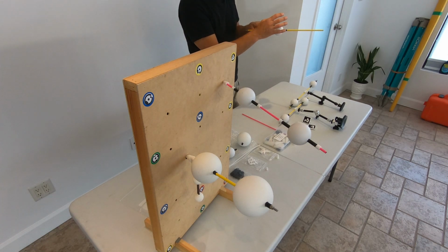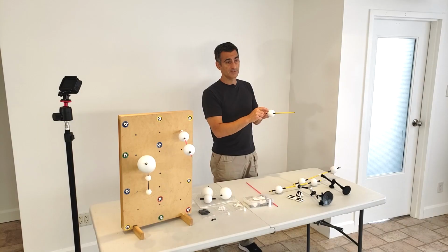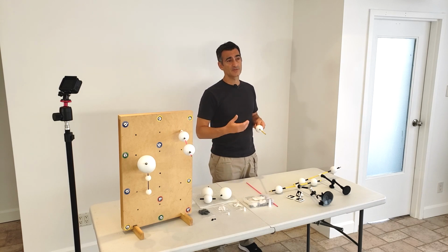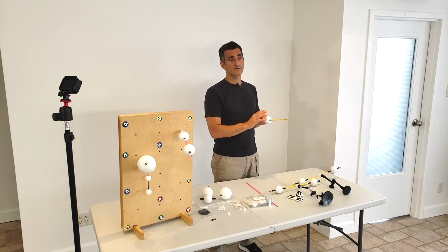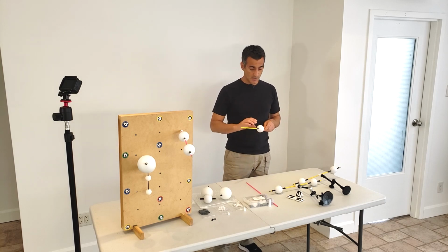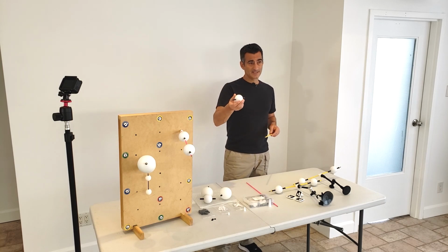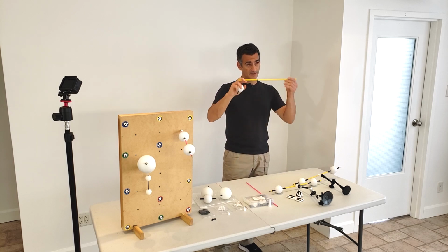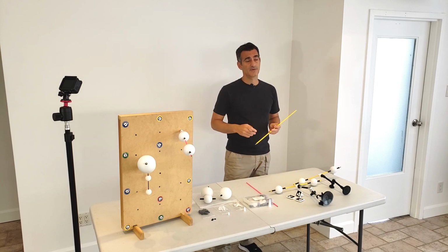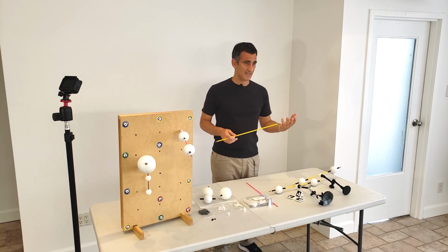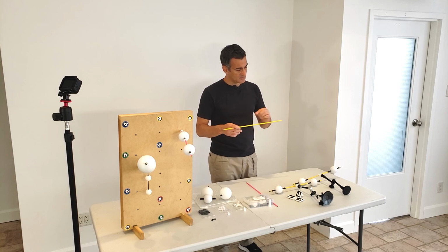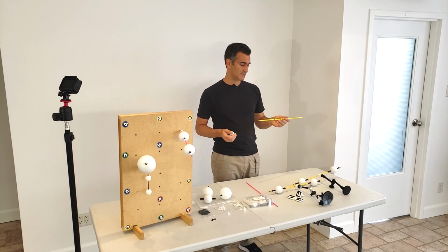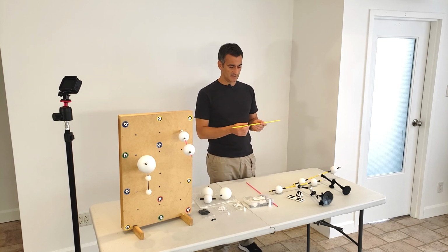And then it's going to average the center of the sphere. So statistically, if I've got 1,000 points versus 20 points, 1,000 points should give me a really good center for this particular sphere. So that's why we use the spheres. They're automatically detected in software, or semi-automatically detected, which saves me a lot of time, because if I just use a rod, a lot of software will require manual alignment. You have to go in and digitally move around a trajectory and try to get it to fit by eye as best as possible. So that introduces some subjectivity.